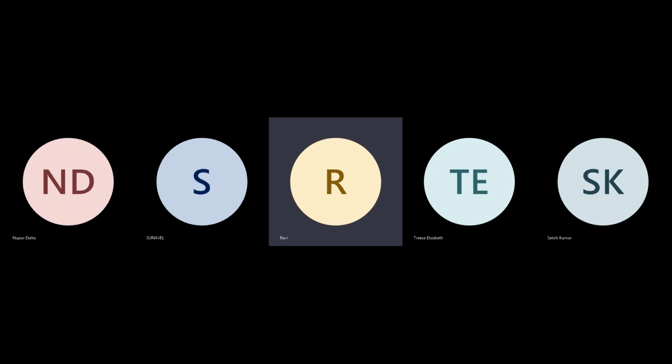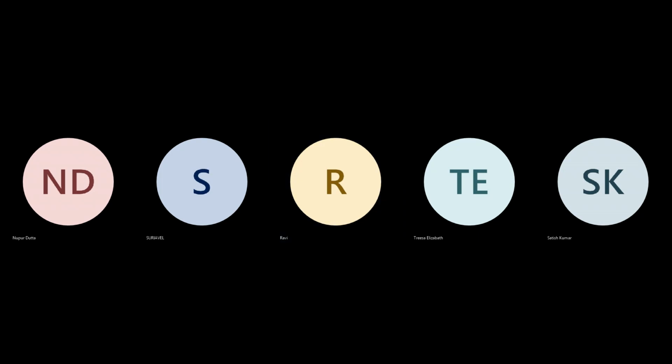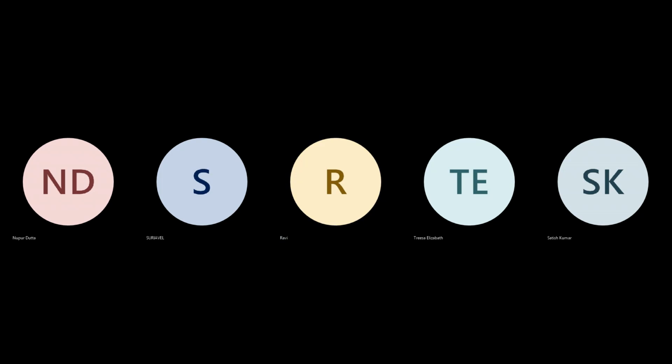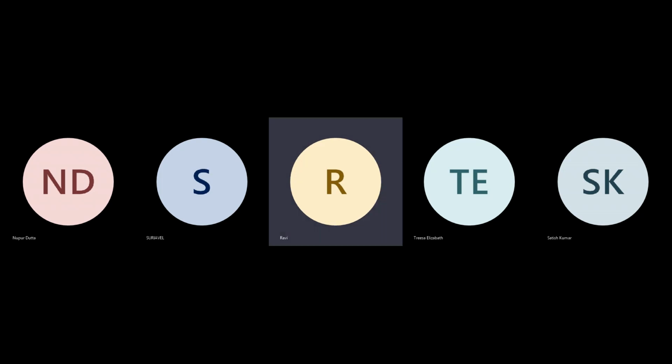You have not defined NDR at placement. It will do a single width. You will see the condition is good, but post CTS, your condition gets screwed up. So defining your clock NDRs and metal layers before placement is also equally important. Clock cell should be of clock type.